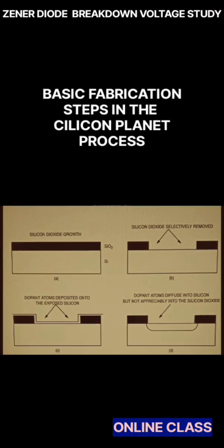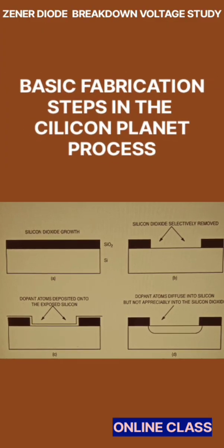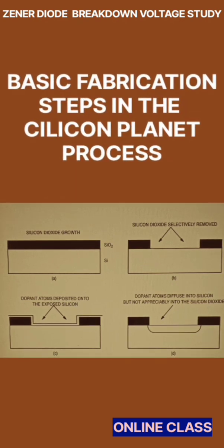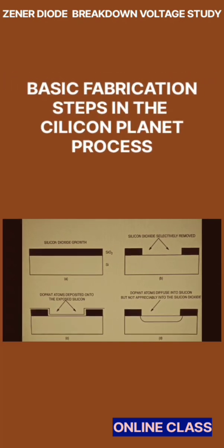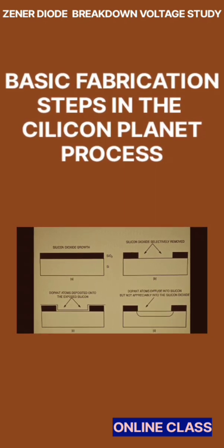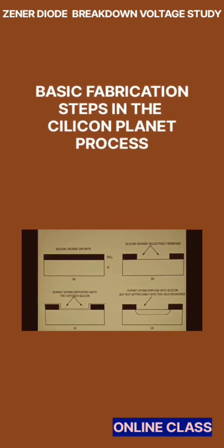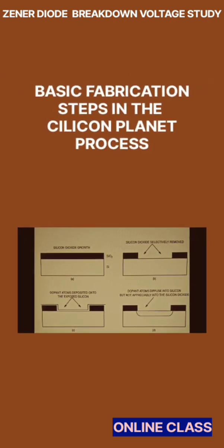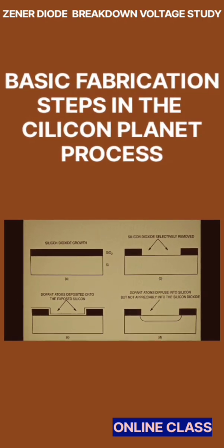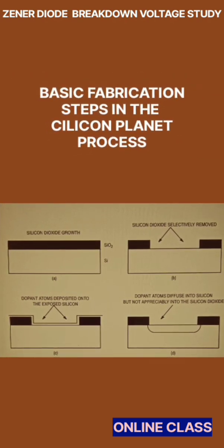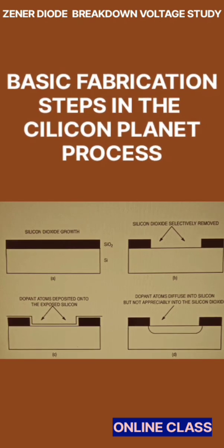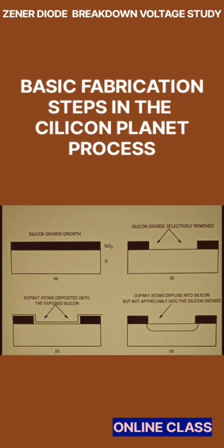After the junction is formed, the wafers undergo a process known as getter processing. This step involves applying high temperatures and slight stress through a highly doped phosphosilicate glass layer added to the back of the wafers. This treatment helps any contaminants near the junction to move away from the area, enhancing the reverse leakage characteristics and stability of the device.